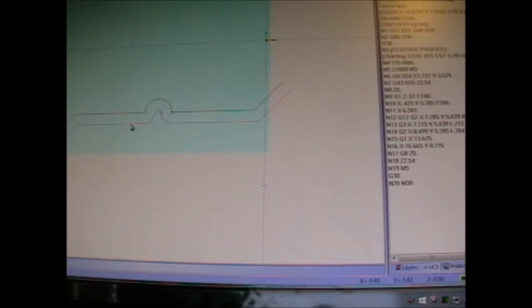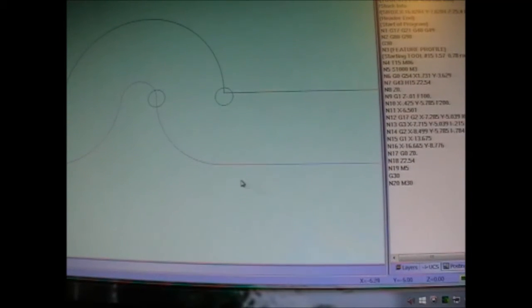Let me just reiterate that key point. Okay, here's our toolpath. We're starting here, we're coming along, and we're entering these three curves. Let's zoom in on that. When we begin the toolpath point of the arc toolpath, which is line number 12, we begin a set of code that needs changing, and we're at this point here, the beginning of the arc. Now, this milling software produces center arc format incremental IJ mode. That will be quite common. I would say most milling software will be like that.